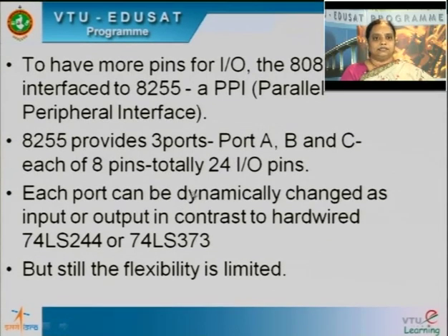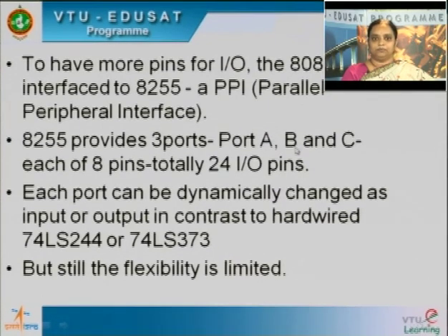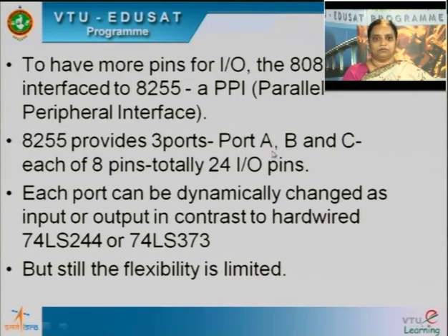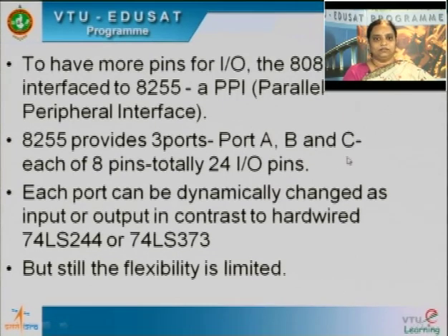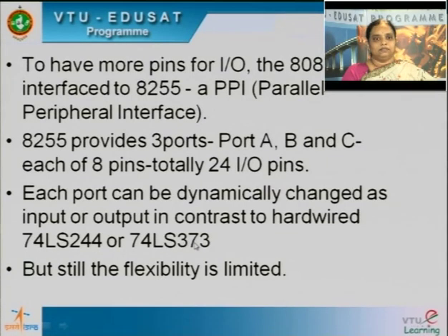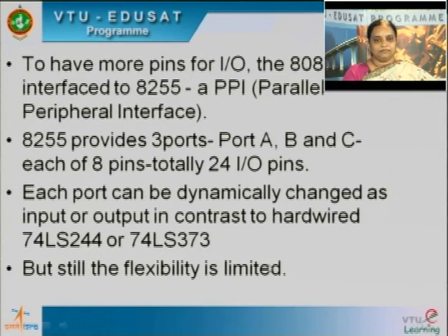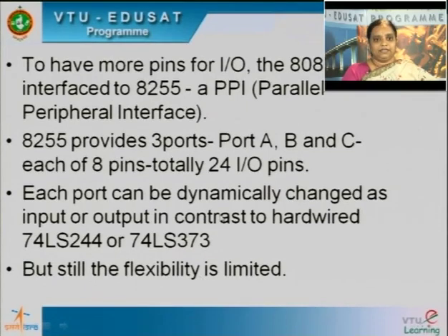One advantage is each port can be dynamically changed. Port A can be input or output. Similarly, port B can be configured as input or output, and so on. Whereas the 244 and 373 which we have seen previously are hardwired, they cannot be changed. But still, whatever flexibility we get is limited.